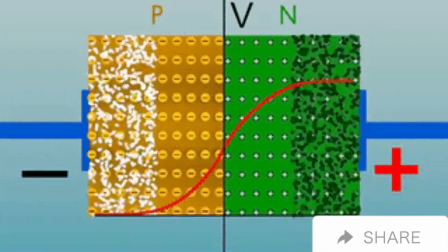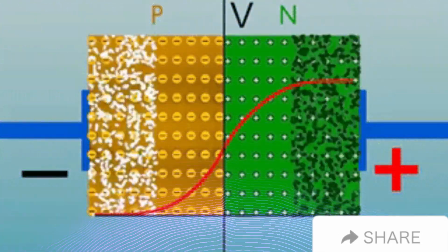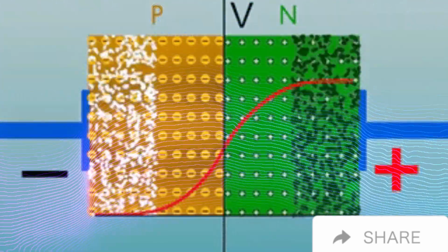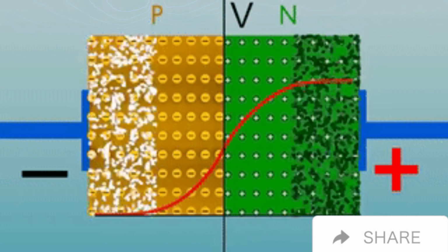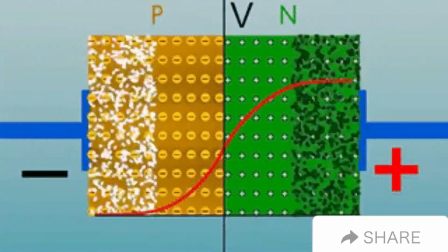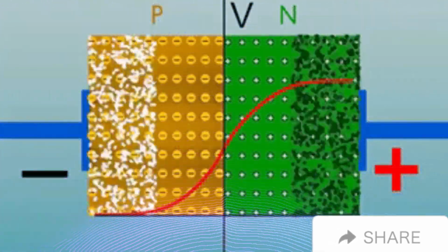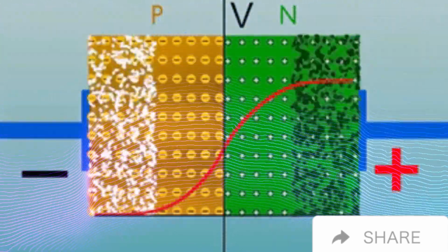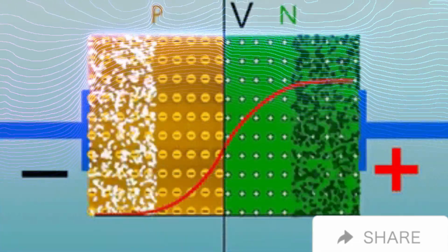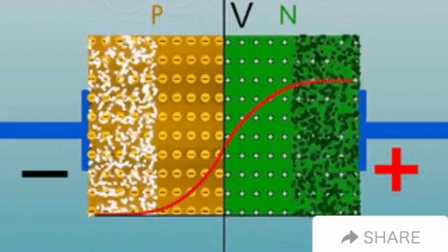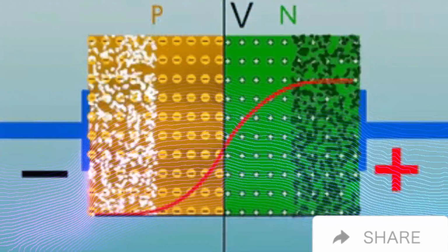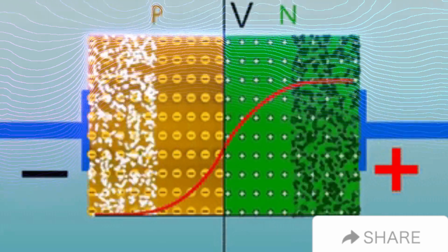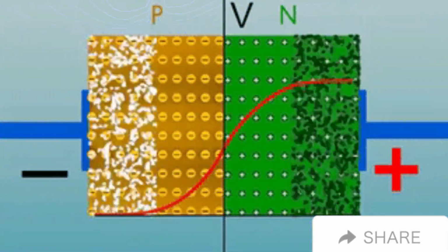Clipping: it can limit voltages of the signal, which prevents them from exceeding certain thresholds or limits. Clamping: it can be used to clamp a waveform to a certain DC level by preventing it from going below. Current steering: diodes are used in circuits for current steering, which ensures that the current flows in a specific direction under certain conditions.